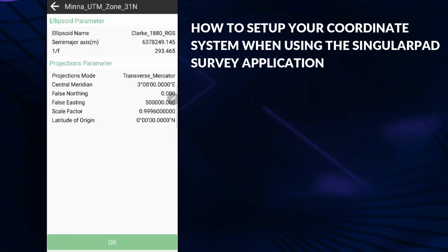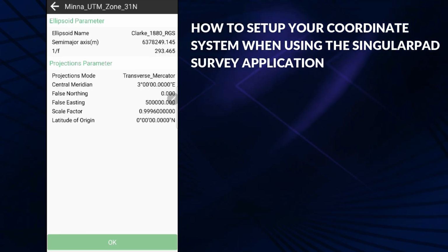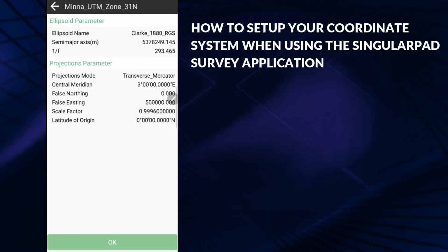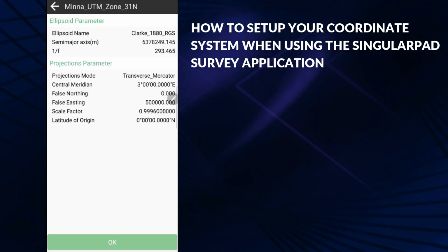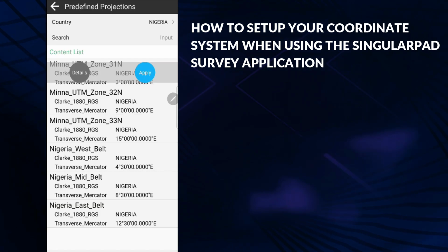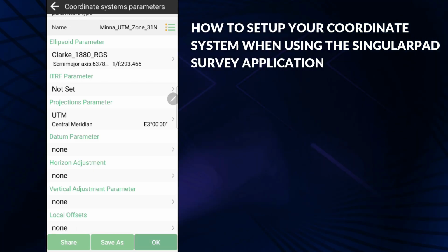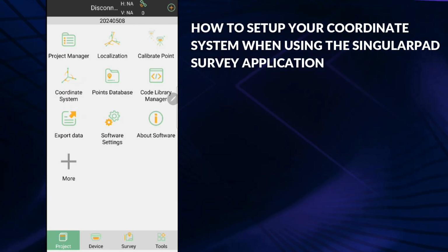So you can just go through it to check if it is the same thing with what you want to use. As you can see, the first listing on this one is 500,000. That is okay. The central meridian is 3 degrees, so that is okay for zone 31. So click OK, and then we'll click on apply. If you want to save it, you can just click on OK, and it has saved to this project, the project that we created.